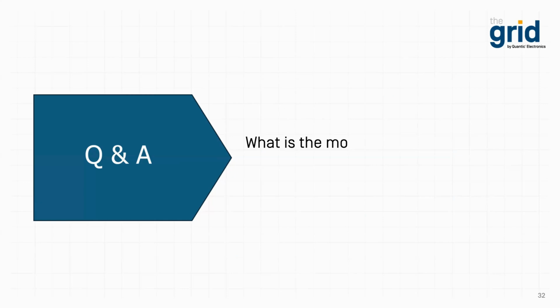Last question, what is the most often seen derate criteria? 60%. That's pretty typical. Some designers will shave that down to 50% if there's a good case. But 60% voltage derate, and of course, you derate by voltage, you also derate by temperature. And you can get an approximate doubling of life for every 10 degrees below the operating temperature that you're operating. So temperature and voltage is what we see. The big one is the voltage derate, and that's typically 60%.